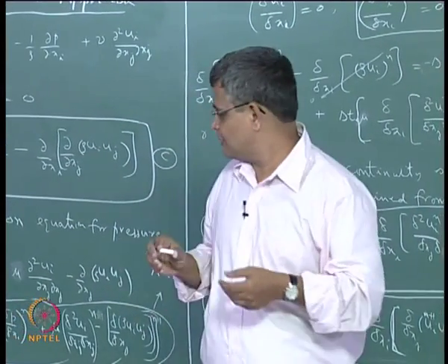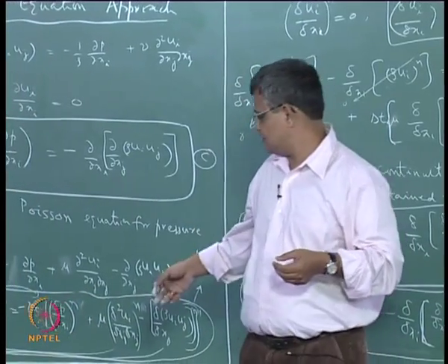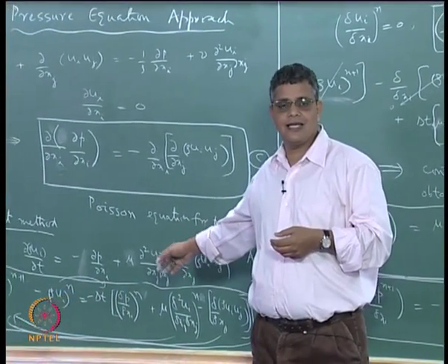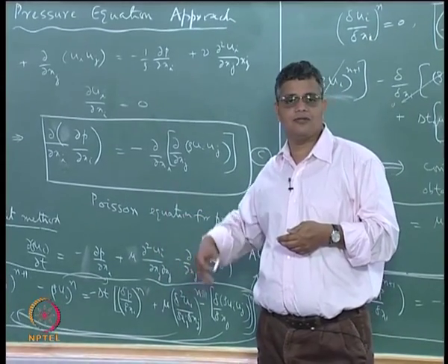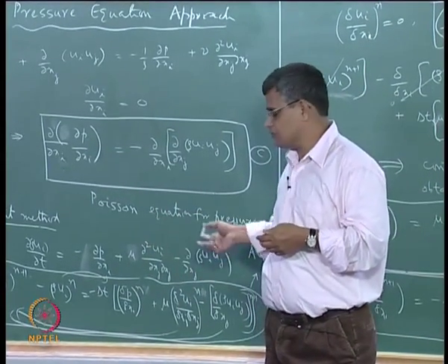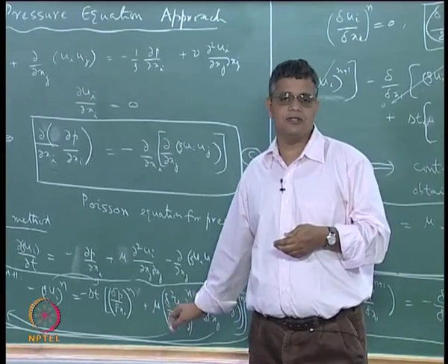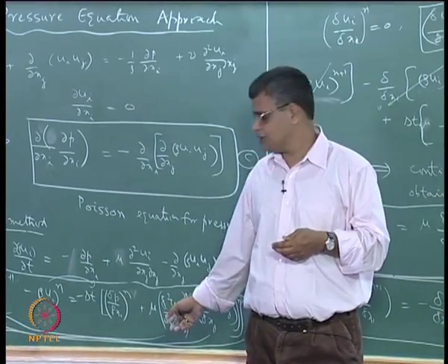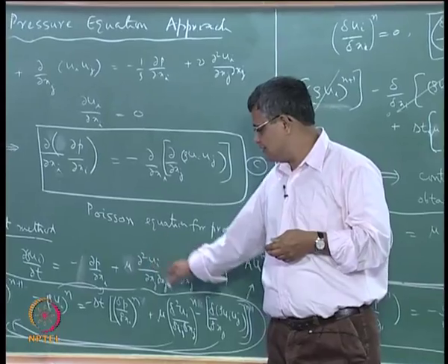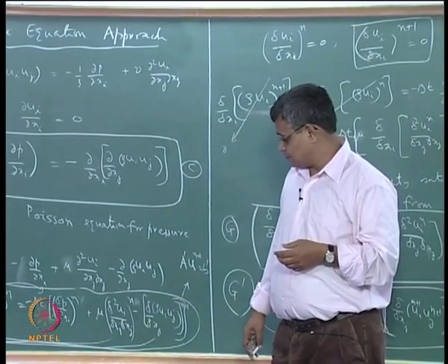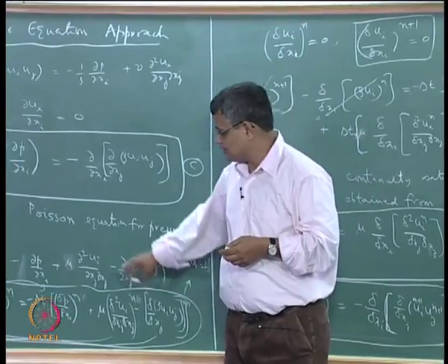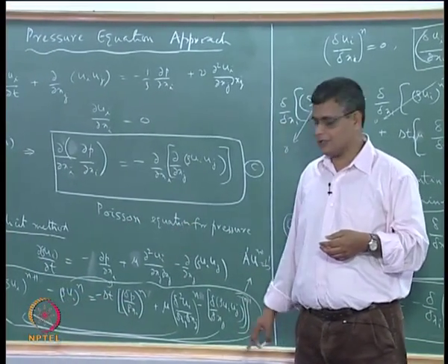Okay, so the time step limitation is associated with the scalar convection diffusion equation. So that means there is a component from the Courant number and there is a component from the diffusion parameter, the diffusivity, which together determine the time step limitation in the case of an explicit method.